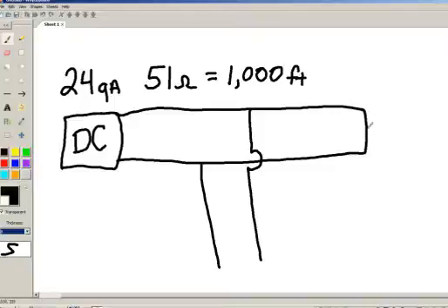It finds the continuity path, and the same thing on the way back. It sees the other side of the bridge tap, but it instantly senses there's no place for it to go. So it ignores it entirely and just goes right back to the meter. So in theory, heck, I could put 50 bridge taps on there as long as they were not faulted. They would have no impact on my DC current measurement used for my ohm meter.